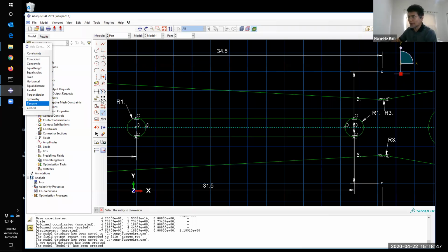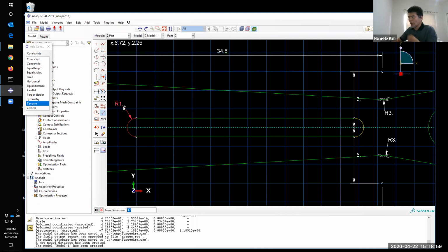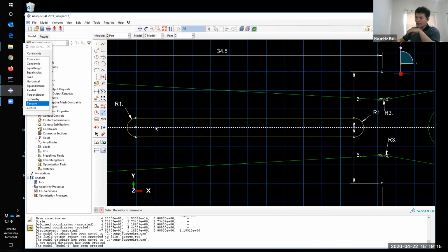But as we experienced before, if you trim, the green color will be gone because now the radius is removed, right? So I will need another dimension with 1, and then another dimension with 1. Okay, but still it's not green. Why? When I create a circle of radius 1, it is on this construction line at the center.